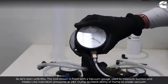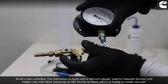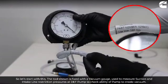So let's start with this. The tool shown is fitted with a vacuum gauge, used to measure suction and intake line restriction pressures at the DEF pump, to check the ability of the pump to create vacuum.